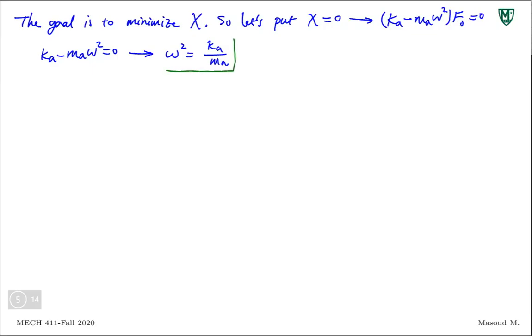This is the golden relationship that you are looking for. So if you know the frequency of excitation of your external force, let's say your system is under harmonic force excitation with a frequency of 10 radian per second, the value of the stiffness for the absorber and the mass for the absorber, to make sure that your structure doesn't move, because of this force, this counter effect is strong enough to make sure that the structure actually doesn't move. It is under force vibration, but whatever force is trying to do with your main structure is transferred or absorbed by the added absorber, spring mass system you added.